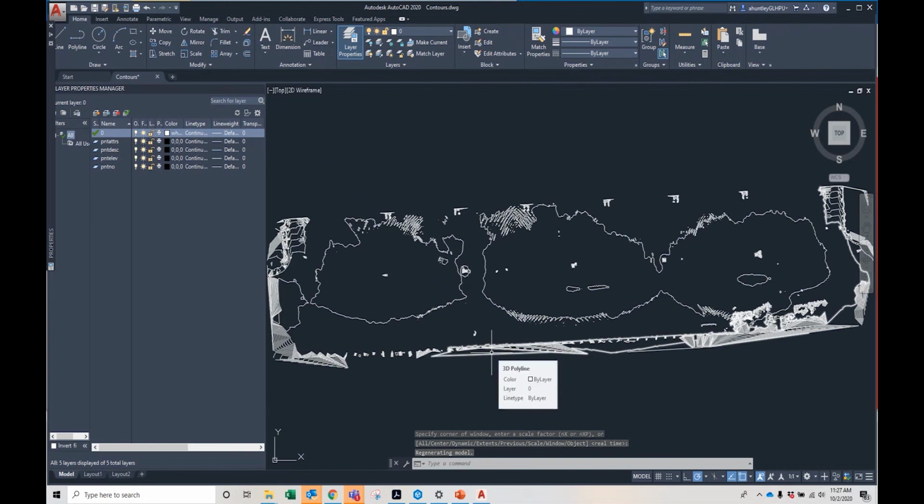There's my contours. So this DWG, it's not the prettiest, but it can work. We can put it right into our Magnet Field layout software, and you can take any of our Topcon robotic total stations and quickly go out and shoot those elevations. What's really beneficial about that is, if you're using the GTL 1000, you can scan at time of placement on concrete. Right when they pour it out of the pump trucks and the placement boom, they rake it in, you scan real quick, create this contour, and you can actually see where your highs and your lows are.